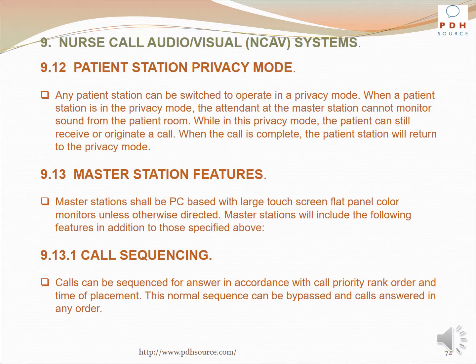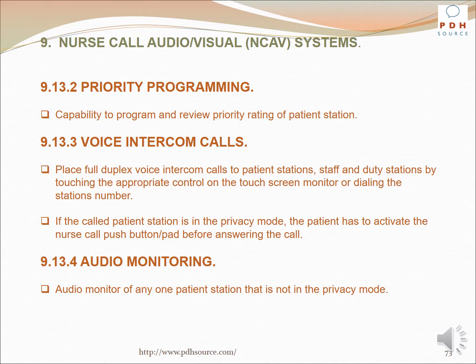Master stations shall be PC-based with large touchscreen flat panel color monitors unless otherwise directed. Master stations will include the following features in addition to those specified above. Calls can be sequenced for answer in accordance with call priority rank order and time of placement. This normal sequence can be bypassed and calls answered in any order. Capability to program and review priority rating of patient stations shall be available.